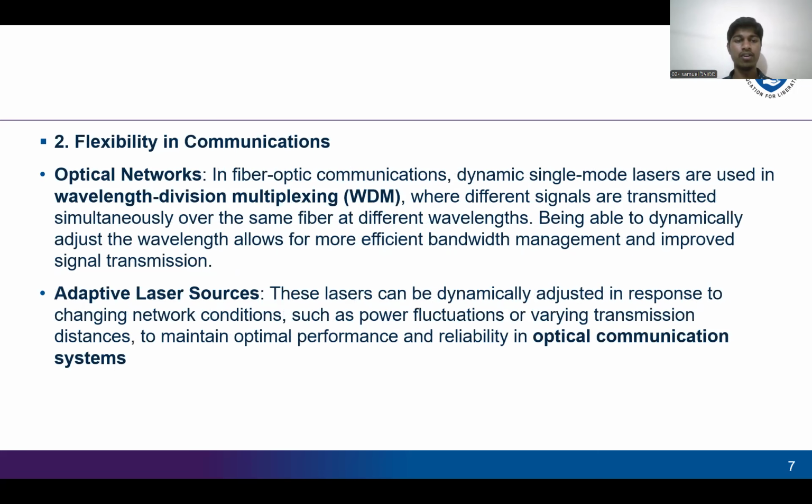Flexibility in communication, optical networks. In fiber optic communications, dynamic single mode lasers are used in wavelength division multiplexing, where different signals are transmitted simultaneously over the same fiber at different wavelengths. Being able to dynamically adjust the wavelength allows for more efficient and significant bandwidth management and improved signal transmission.